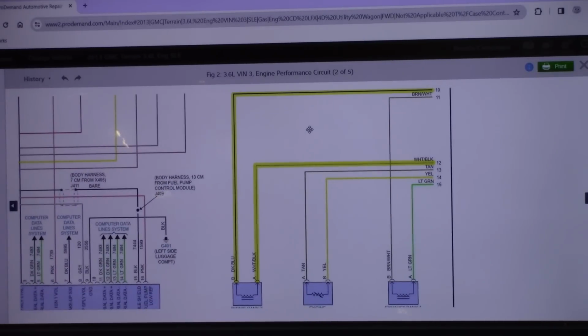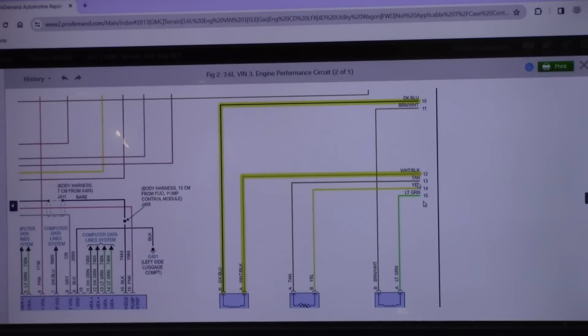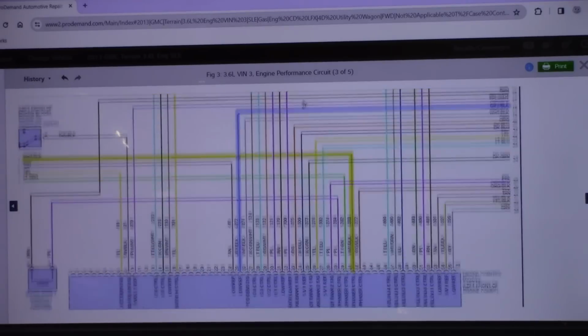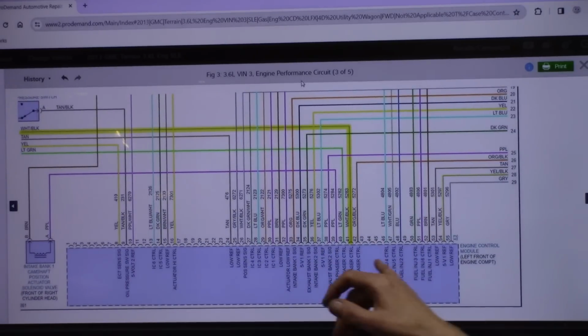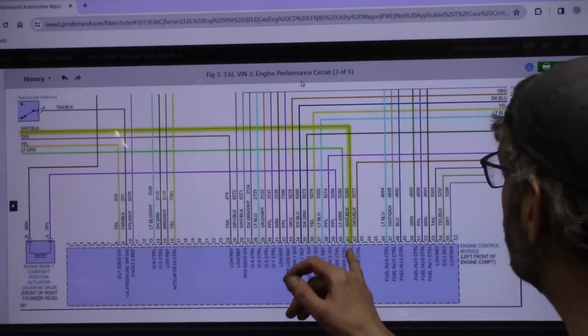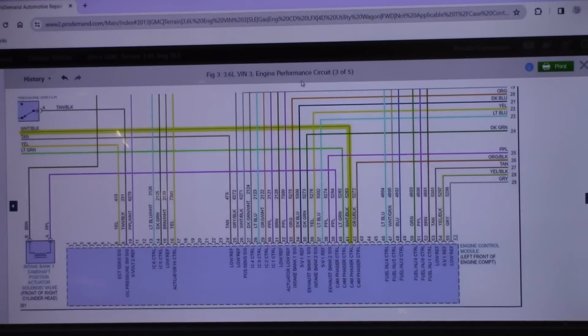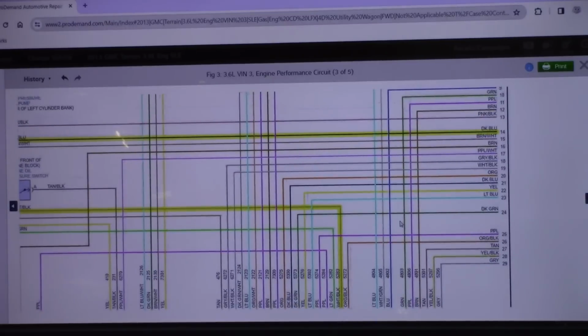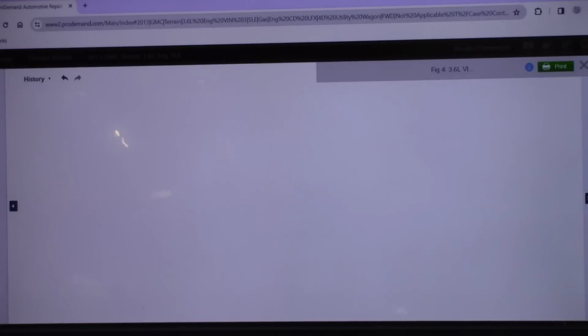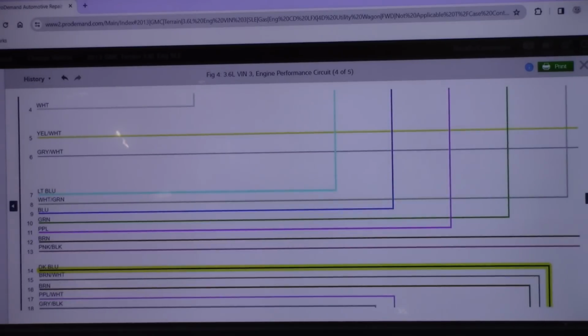If we highlight our wires here, we go off the screen to 10 and 12, it looks like. We follow along. Okay, so one of them branches off and we've got our cam phaser control. Okay, so I'm kind of liking that. That means if our other wire, which is here, goes off to a ground, then we've got a power side controlled solenoid there. So let's follow 14 off.